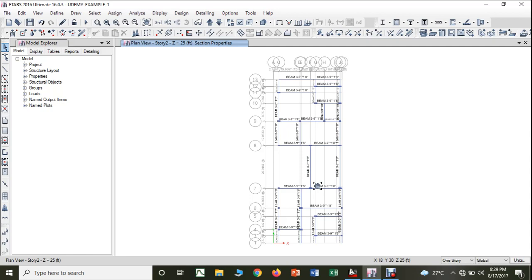When I go to the loadings, I'll clearly explain. If the live load on the ground floor, that is first floor, is 3 kilonewton per meter square, I can have only 1.5 kilonewton per meter square on the roof. Because if there are no floors above, then it is not a floor of living. It will be just for recreation purposes. Therefore, usually half of the loads will be considered.